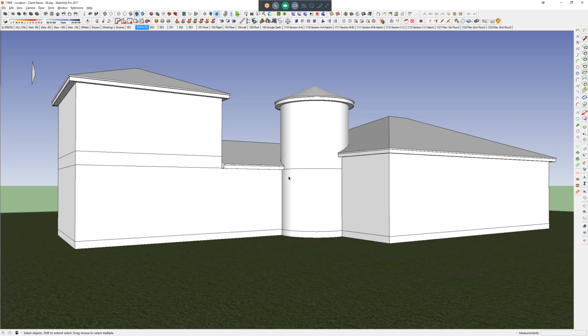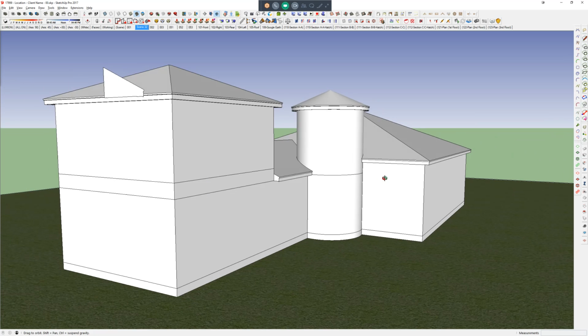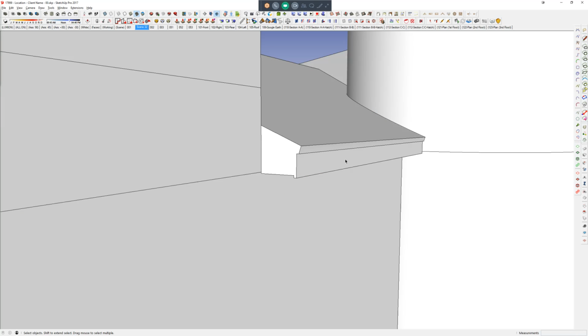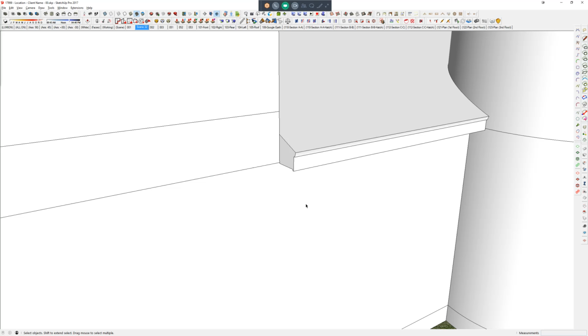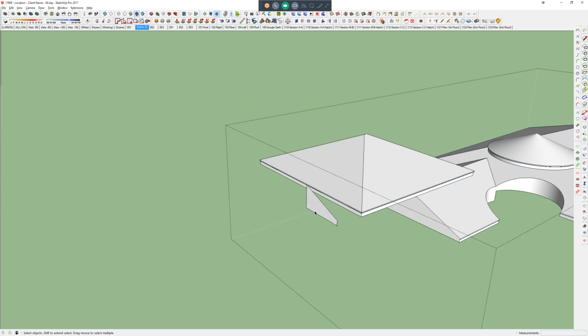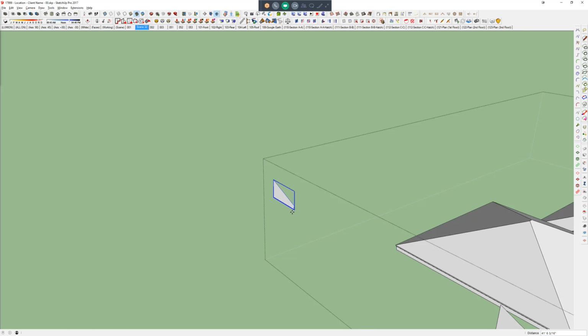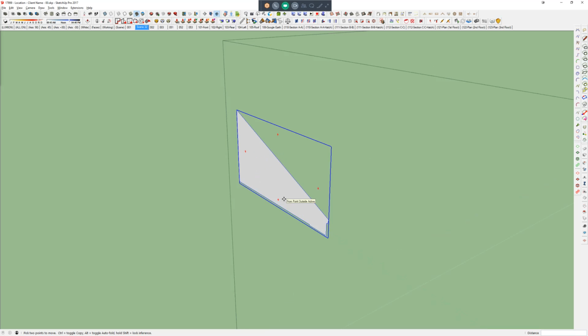So now let's talk about one other very important piece, gable ends. Even though this doesn't have a gable specifically, a lot of times we end up with these areas here that really would be a gable. And the way I deal with gables is I essentially create a gable jig that I can copy around wherever I need to. So I'll leave this cut flat just like that, and I'll build a gable jig, and I'll show you that. This will take a little bit of setup time, but once you do it, you can build a gable anywhere in the house that you need to.